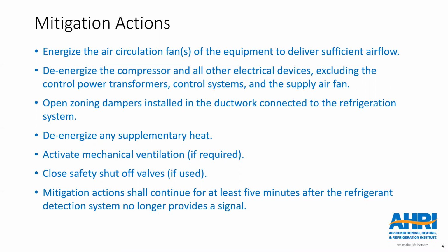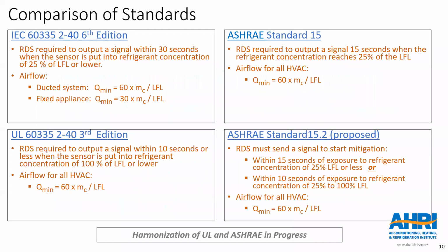And these mitigation actions need to continue for at least 5 minutes after the detection system no longer is sensing refrigerant. So those are the key things that happen. The next slide will talk about the subtle differences.